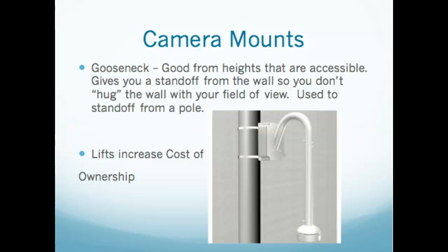Anything over, say, 17 feet, in fact, I would even say 15 feet, you're going to require more than just a ladder to get up to work on these. You can't rest a ladder against a round pole safely, so you'll need a step ladder. And think about a step ladder. I have a 10-foot one at my home. I think they probably go to 12 and maybe even 15. Maybe there's a 20 out there. But how safe do you want someone to be when they're working on these things if you go up too high? So a lift is required to safely get up to these things.